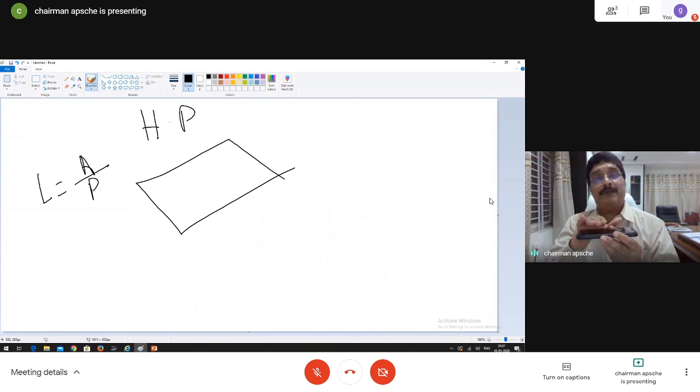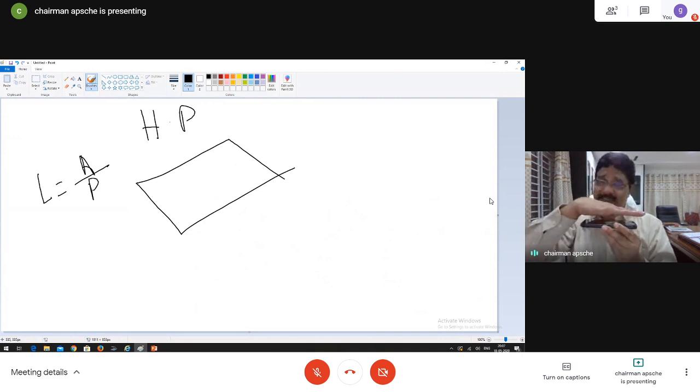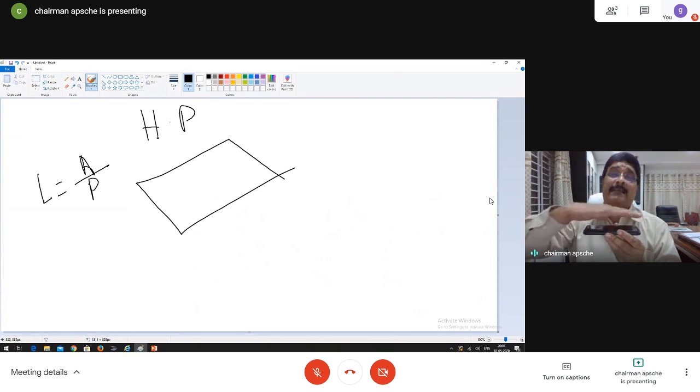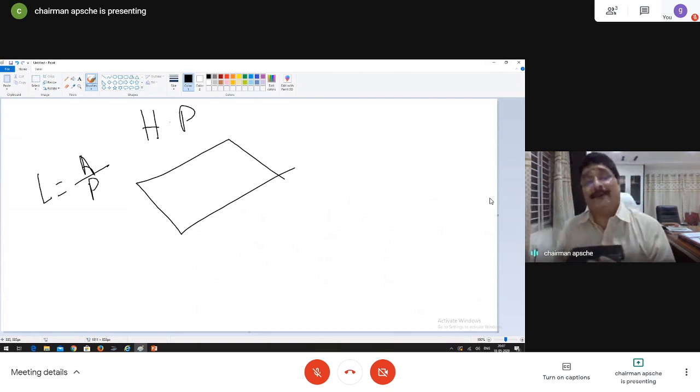The heavier molecule cannot go up, it sits pretty on it. Now, the next molecule comes, it either interacts with the plate or the already settled heavier molecule, and it also loses its heat. This also sits heavy. Now, what is happening after some time? Layer after layer, the hot molecules are coming, giving away the heat to the plate, and now they are settling because they cannot move. They have become heavier. Buoyancy force is reversed now. All these molecules, upon losing their heat, are coming and sitting here.